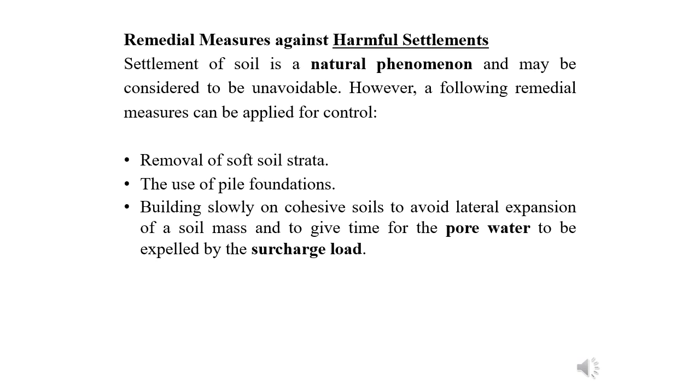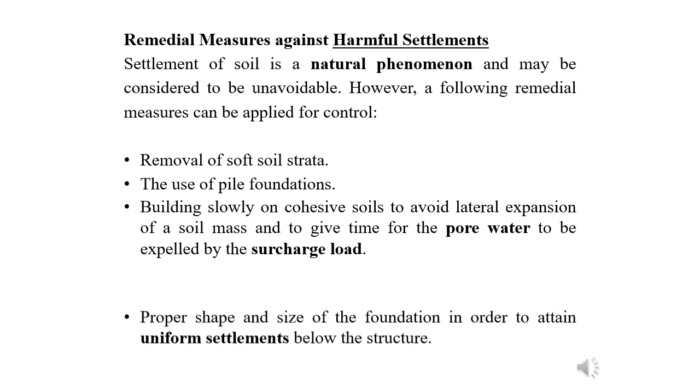How can we explain it in a proper way? Suppose soil is saturated, and you are going to start constructing the structure. So in that case, you have to allow the pore water pressure to release so that the structure will come to only the solid particles. So this will also control the settlements.